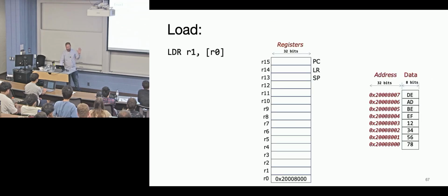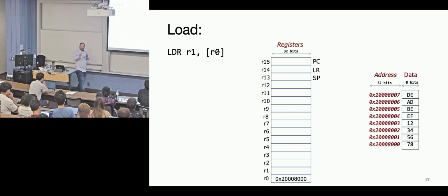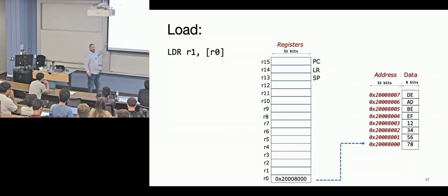So here is just a normal vanilla load instruction, and store obviously works the same, just in reverse. Here we have R0. It defines the address from which we're going to get data. And then we're going to place that into R1. So we're going to use R0, look at that address, and take out a 32-bit value. This is a 32-bit operation, it's not LDRH or LDRB.